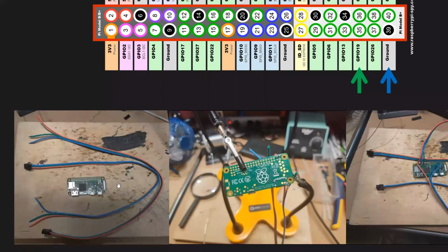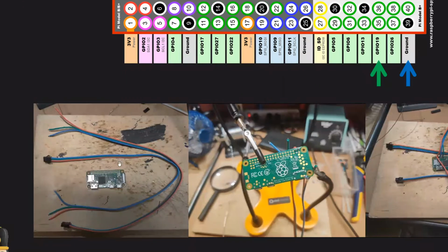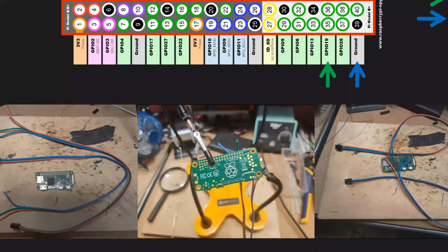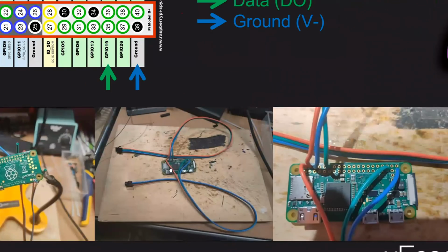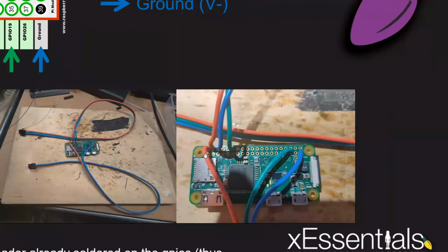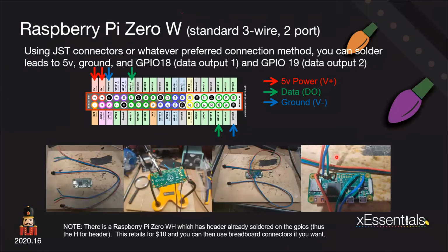So to start off, here's our little Raspberry Pi. Here's 2 really long JSTs. Set it up in my clamps. I'm over 50, so I need my magnifying glasses to get it all to work. Solder it together. When you get done, here's 2 leads. And just like that diagram of the pinouts, red, red, blue, a couple of spaces and a green. And down here, a green and a blue. And voila, we have a controller, 2 JST connectors that we could plug in.